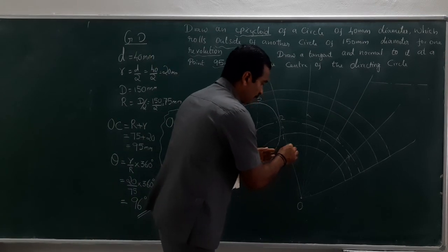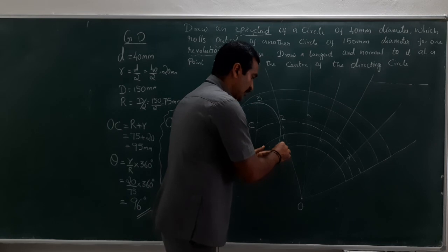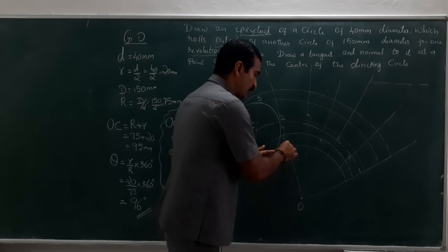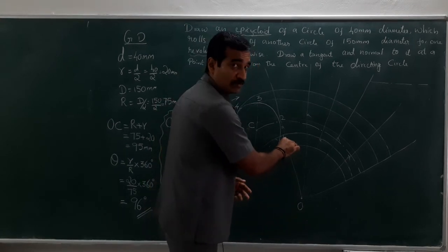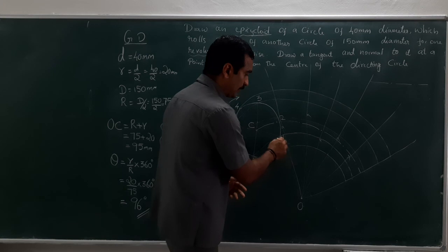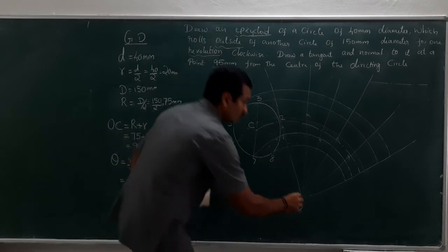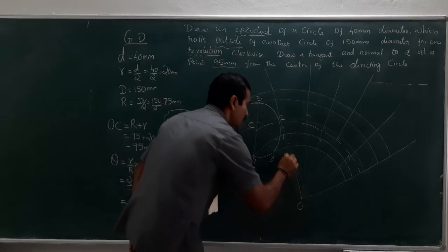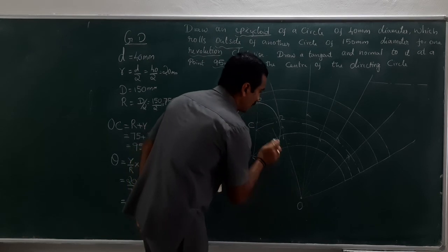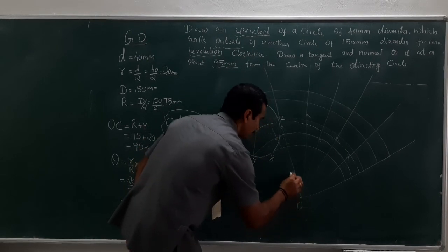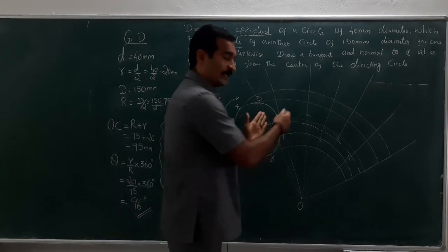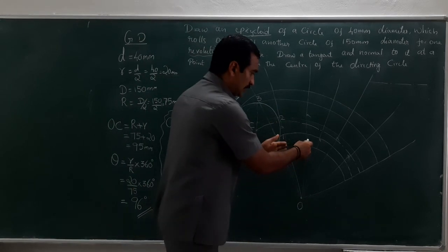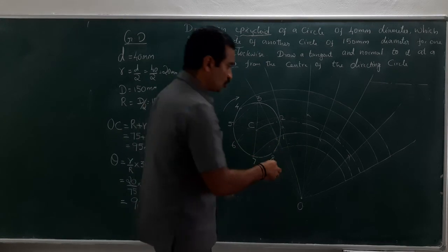Now, these are my extreme points. Stretching the compass to take more than half of this particular arc, cut an arc here. Now, change the location of the compass and keep one leg on this extreme point, cut an arc here. Now, from O, draw a line passing through the intersection, right. Fine, this has been divided now. This is the portion, finally I have to divide into 2.